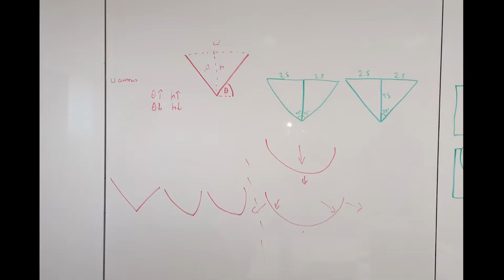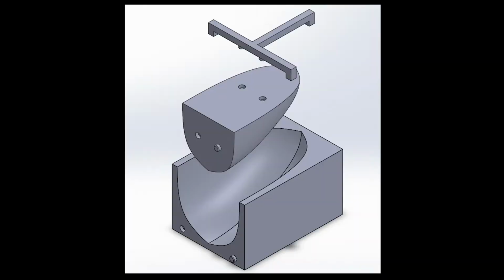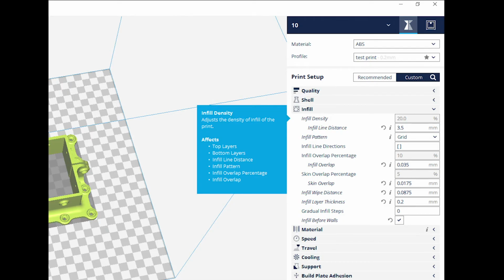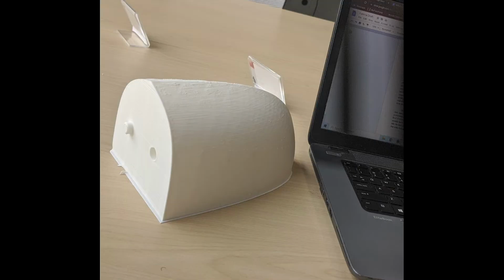After deciding what our concrete would be made up of, we had to figure out how to actually shape it. This started with a debate on how V-shaped the cross-section of our canoe would be, and after exchanging multiple emails with our project guru, we eventually decided on the shape and were able to create a 3D CAD model of our canoe mold, which we then 3D printed at 5% infill. Despite such a low infill percentage, each of our insert pieces took 13 hours to print, and our outer mold would have taken 26 hours per piece to print.